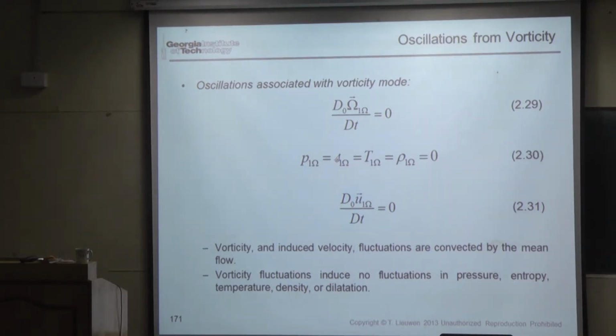It's a well-observed fact that vortical disturbances make sound. All right, jet noise is a great example of that. Jets have turbulent fluctuations. The fundamental mechanism is that you have fluctuations in vorticity, and it's making lots of sound. When you hear a subsonic jet flying by and you hear that noise, you're hearing vortical fluctuations. So how does that observation jive with what I wrote here, where I said P1 omega is equal to 0?